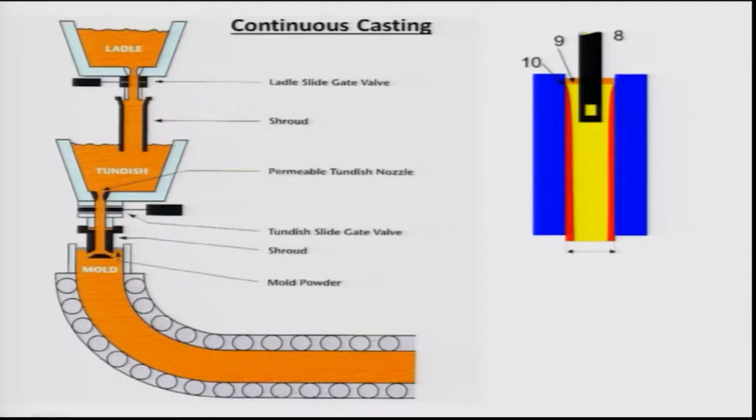So this is basically a chilled zone in which the liquid metal has been solidified very rapidly because it's copper and also water cooled, so the heat transport is very high. So the number of sites on which nucleation can happen is also very large. Not only that, because it's a rapid cooling process, the sizes of the grains which may form along this interface are very small.